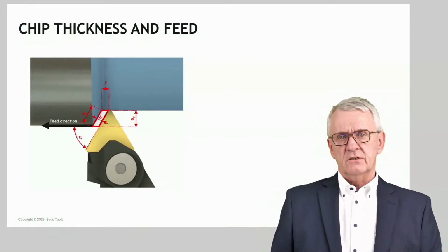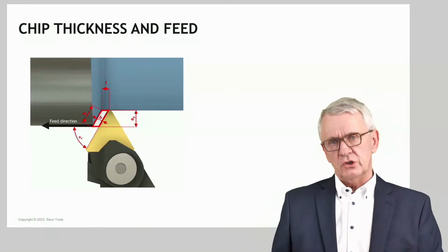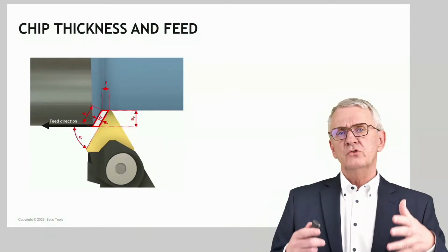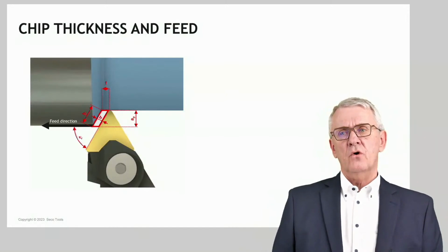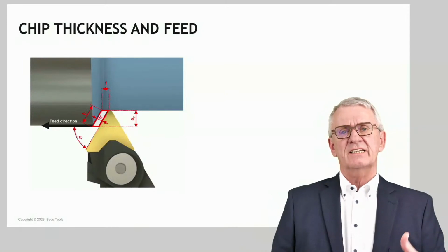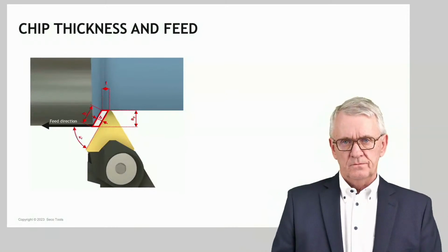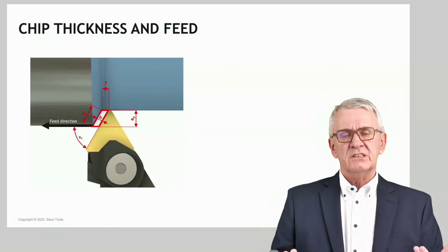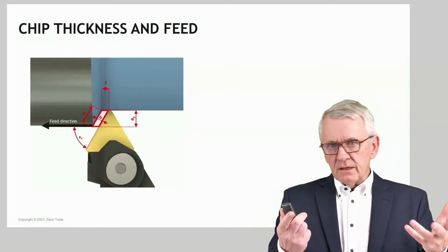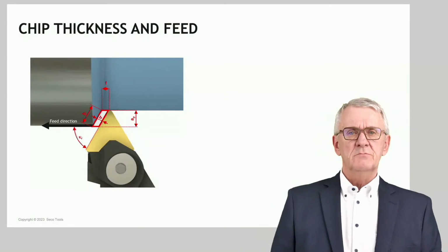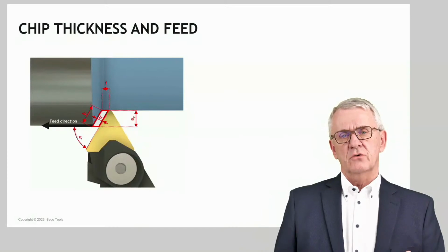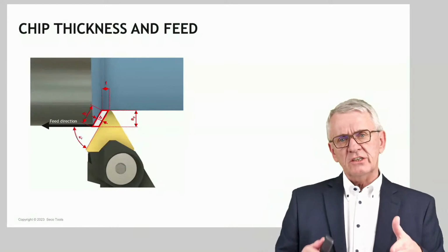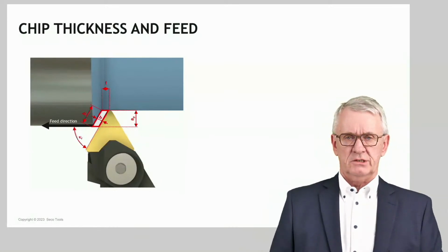The other set of cutting conditions, also referred to as the technological cutting conditions, refer to the cutting edge. The cutting edge is your reference. And then we talk about the thickness of the material that the cutting edge needs to cut. The chip thickness. Careful again, remember? Chip thickness, symbol H in the picture here, which is the thickness of material a cutting edge is going to cut, and it's measured perpendicular to the cutting edge line. So the cutting edge becomes now my reference.